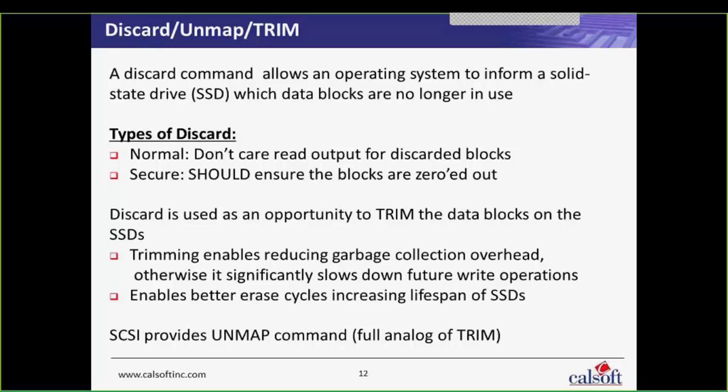So discard and map trim. This is an interesting problem that solid state devices normally face, and it has been in this industry since the birth of solid state devices. A discard command allows an operating system to inform the solid state drive which data blocks are no longer in use.